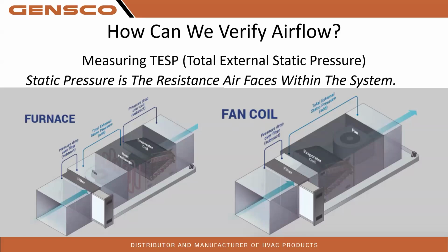It's just like us using our online diagnostics. It might tell me it's moving this much airflow, but is it? Because that feedback is just based off of the RPMs and the amps of that blower. I don't know what's happening in the field. I'm just looking at numbers. Same thing with you in the TrueFlow plate. Let's make sure we are using our tools, all of them, to get the information we need.